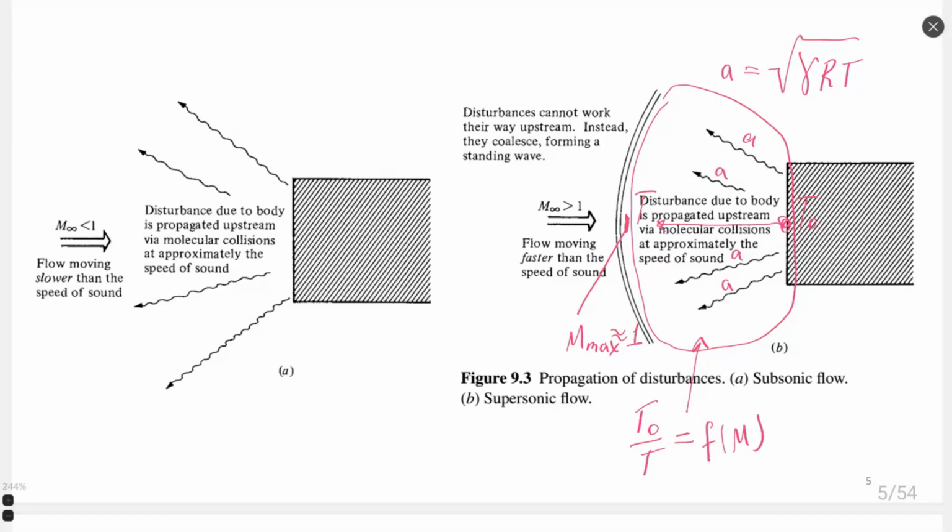No, not possible, but probably I can just write that we will find that for this case, when we have a transition from Mach 1 to stagnation conditions, T0 divided by T would be equal to 1.2. So we see that the stagnation temperature on the wall is at most 20% higher than the temperature after the shock wave. So we can have this rise of temperature.